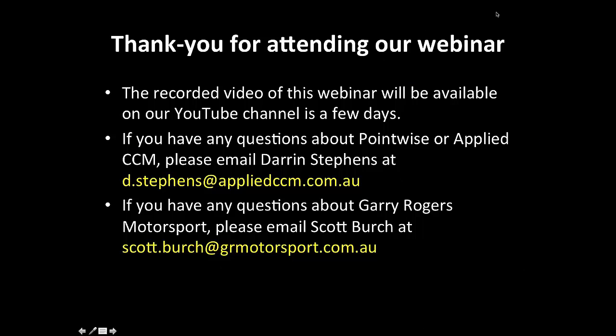You could even change the exhaust and have a significant effect on the aero of the car in that way. A few things you're allowed to do for tuning the car, as Darren said, brake ducts. You can also change your intake ducting. Get an idea of things like blanking. Sometimes you'll blank the engine right up to go out there for just one hot quali lap, and you can make quite a bit of extra downforce that way, and it's good to get an idea of what you're up for when you head out like that.